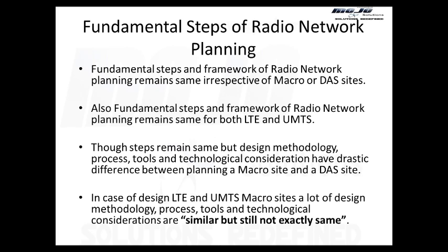The framework, or the end-to-end steps which we discussed earlier. Also, the fundamental steps of radio network planning remain the same on both LTE and UMTS. The steps remain the same, but design methodologies and technological considerations, I mean, what is the signal level, how the signal will be distributed, all those things, have a very big difference in the case of macro site and the DAS site.